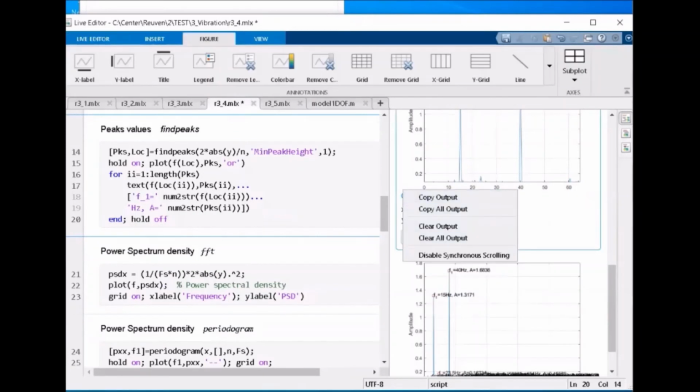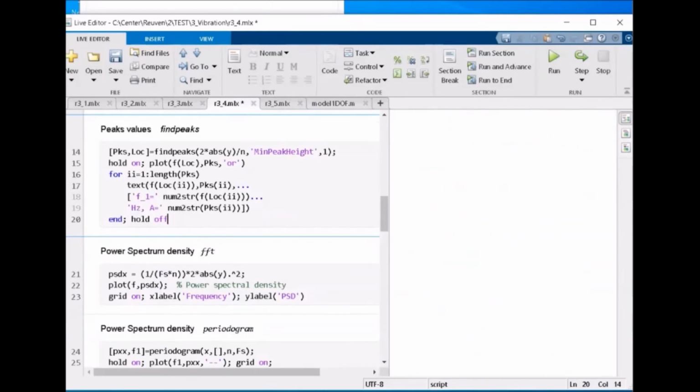Let's continue with FFT. What's the problem? The FFT is a very good, nice command. It can just estimate the spectrum, but there is one very, very serious problem with the FFT. When we produce the FFT from random samples, our Fourier coefficients also are random. When we produce this FFT several times, each time it will be random. We cannot make some average estimation and decrease the error of our estimation of frequency, or maybe estimation of amplitude.